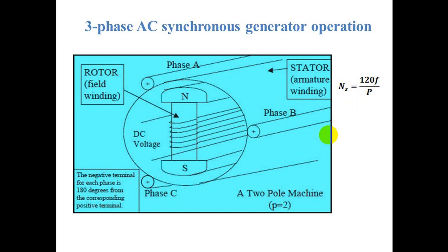In general, synchronous generators consist of two parts, rotor and stator. The rotor part consists of field poles and the stator part consists of armature conductors. The rotation of field poles in the presence of armature conductors induces an alternating voltage, which results in electrical power generation, as shown in these pictures.